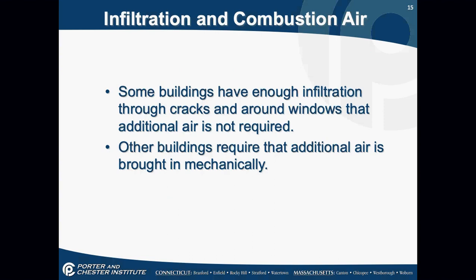Other buildings, especially newer construction, require us to bring in additional air mechanically. The tighter the house, the more combustion air problems I'm going to have. Let me repeat that. The tighter the house, the more combustion air problems I'm going to have. Because the oil burner uses room air for my combustion process.